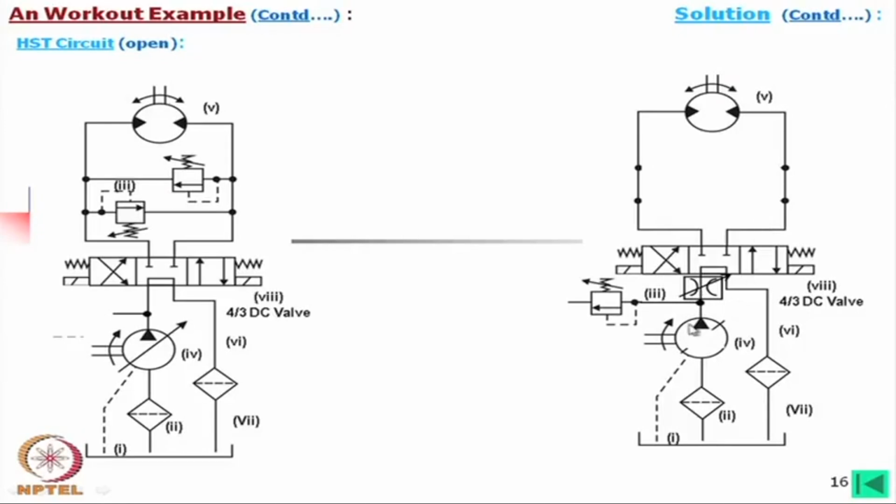So, usually if we would like to rotate for a very short time, a flow control valve will be better than this variable displacement pump. With a variable displacement pump, you have to make the pressure ready, everything. So, there will be a sluggishness in the response. So, these are the differences. Anyway, depending on the cost optimization, you can select which one to be used.